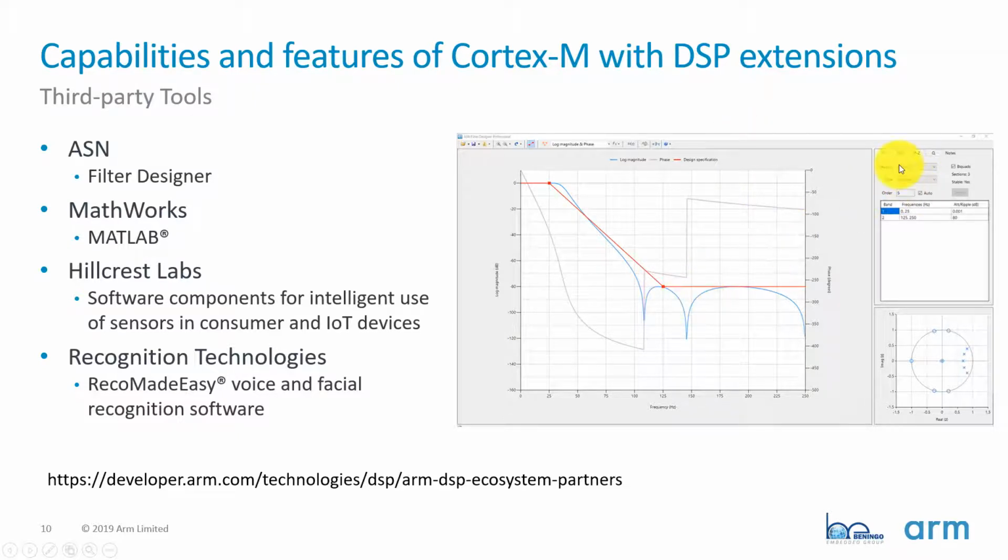Or I can go in on the right hand side here and select the filter type, what method of filtering I want to do, and this tool will actually generate the algorithm automatically for me, and I can take it, copy, and paste it into my code. And then if I need to make adjustments, I just come back to the filter designer instead of some Excel spreadsheet, and then have to keep redesigning everything. So it actually generates the coefficients and even the calls into the DSP library that are required to make the algorithm work. So that ends up being pretty cool.